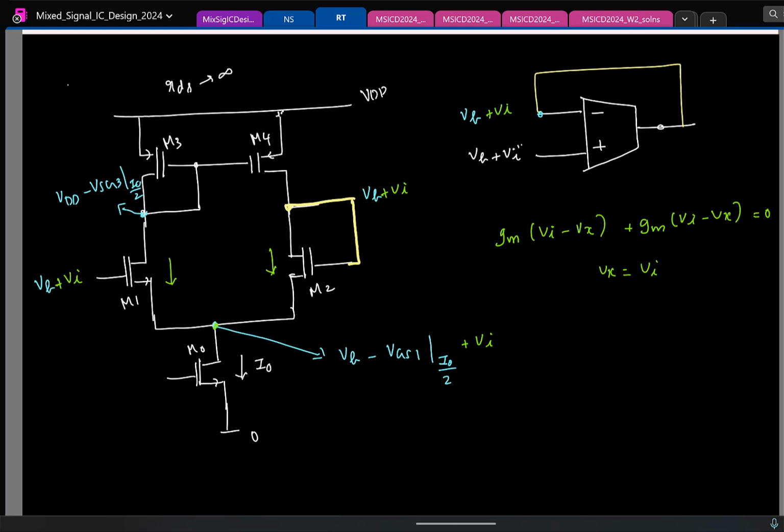So now can you tell me the incremental current in the transistors now? How much will that be? 0. Gm VGS. VG is same as Vs in our approximation. So the incremental currents are all 0 because we have assumed the RDS to be infinity. In practice, it will be very small. If we included the number, the final results will change slightly, but it's okay.